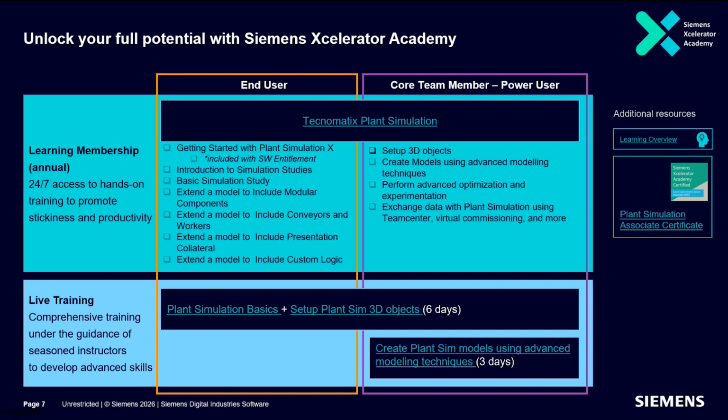Okay, you can only attach parts on the main part, but not directly on the part on the main part. And if you want to do this, then you need to use SimTalk. You can easily move parts on, for instance, the content of a part, and move the part on this, but not directly with the assembly station. But it's really easy with SimTalk.